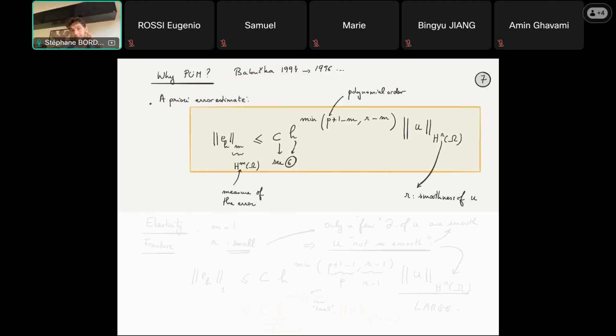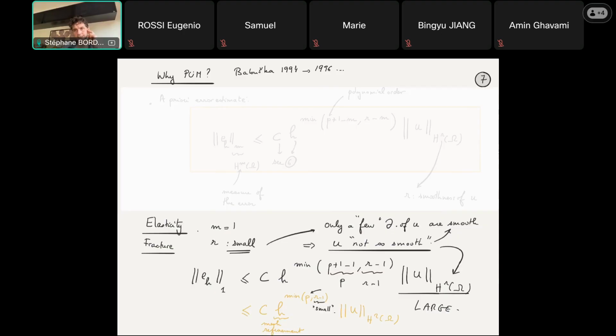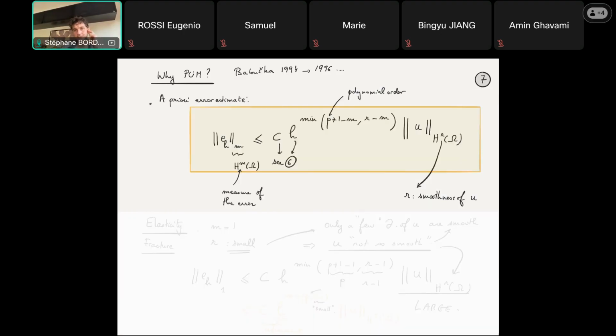So if we want to do better, what can we do? That is the idea that Babuska had in 1994 with Melenk, Markus Melenk, who is now a professor in Austria. They came up with this fantastic idea to say the finite element approximation is as good as the worst interpolant. As good as the worst interpolant. So that means you can increase that p as much as you like. That really doesn't matter at all, because if your r here leads to an infinite value, well, you're done. You can do whatever you like. It will simply not change anything anymore.